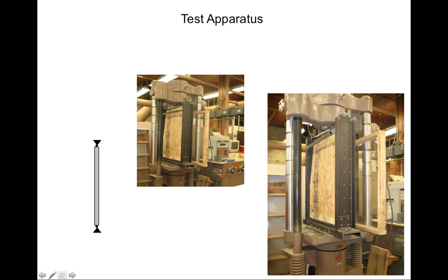The load is then applied to the jig, to the column, and then the column is designed so it will buckle, because basically we want to test this column in as long a length as possible, but our machine only allowed us, say, 45 inches. So we ended up building it so that it could basically rotate at top and bottom in this manner, and in that way we basically induced some type of buckling